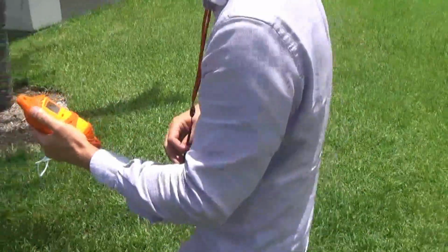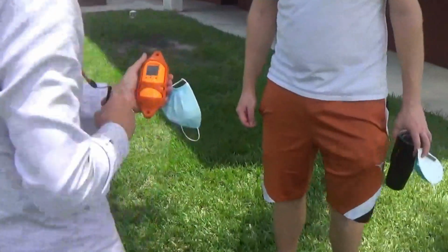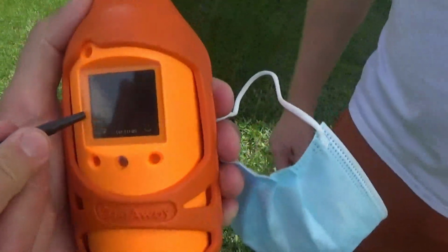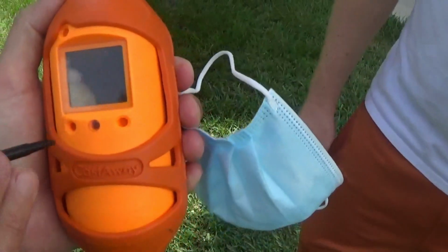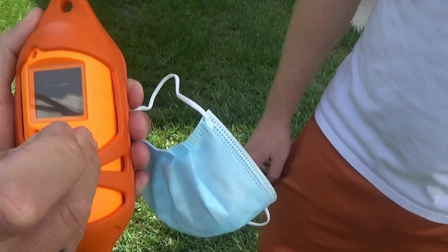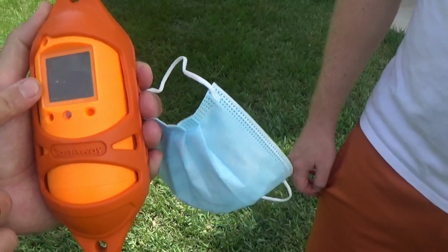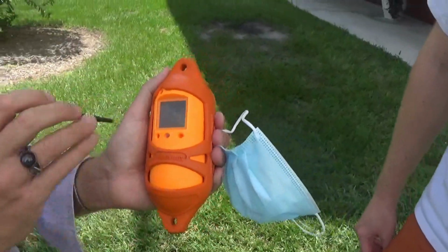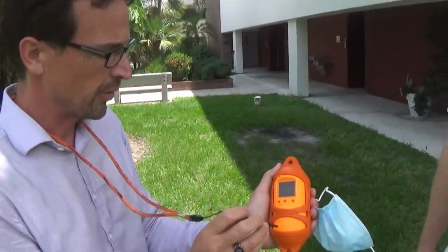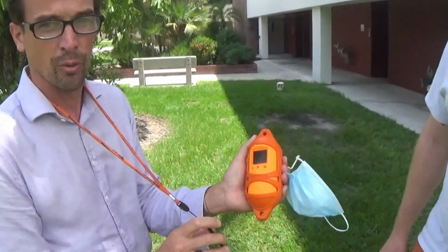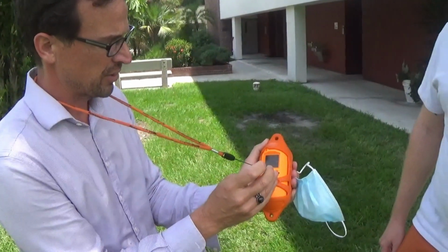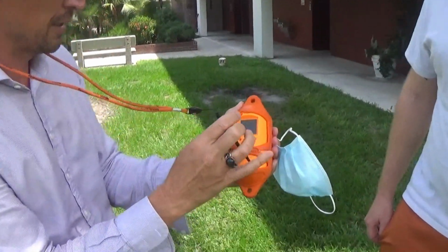Go back to the machine. Okay. You can see that. So we start here on the Castaway icon. We hit the go button. It's going to take a latitude and longitude reading for the start of the cast. If you have good GPS, you can wait for that to happen. Once the reading comes up and you're ready to go, you push the stylus into this hole again, and